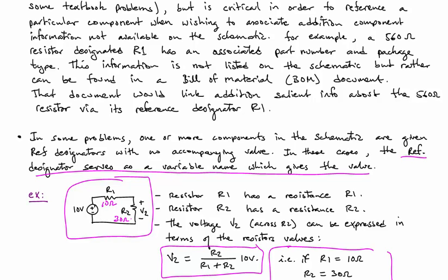And so there are things like maybe specific part numbers. So you might buy a specialized resistor, or this resistor has a certain tolerance and a certain temperature coefficient, and it has this package, and it's been qualified for this temperature environment, all that. And so there's actually a model number, a part number for that specific type of 10 ohm resistor. And that information is not shown on the schematic. It would clutter it too much.